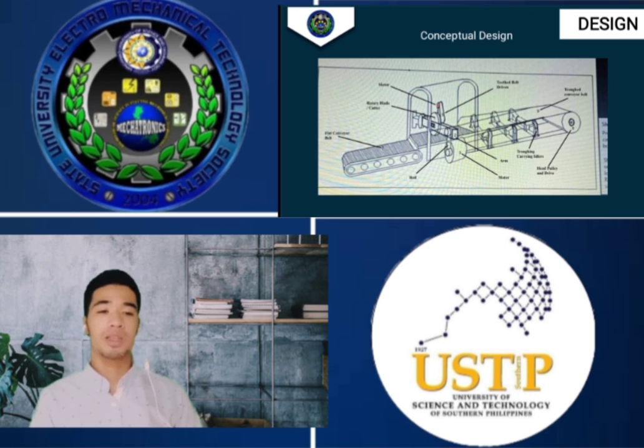For the cutting mechanism, we use rotary cutting. The blade rotates continuously. It is connected to the motor with a toothed belt drive to lessen the vibration. In order to achieve the desired length of the fiber, we are using a shaft encoder sensor. It is connected to the motor. After the fiber is cut, it will transfer onto a flat conveyor belt.